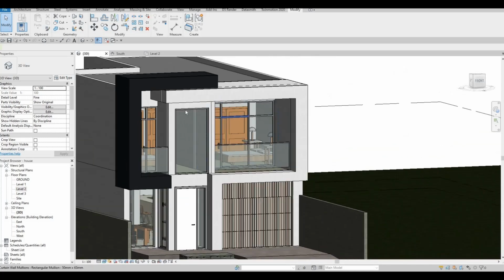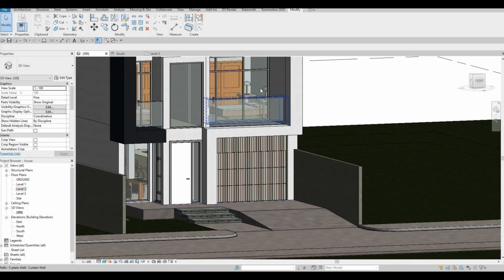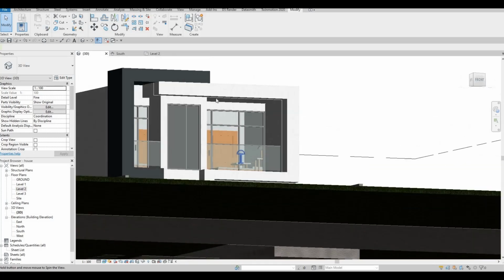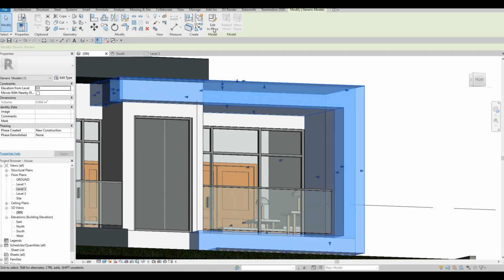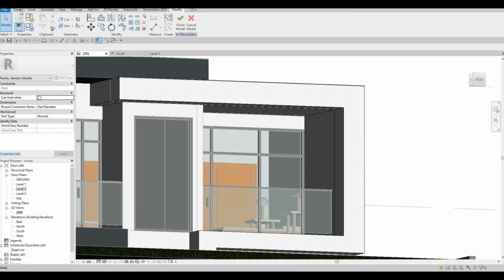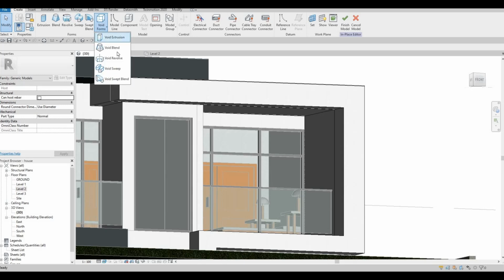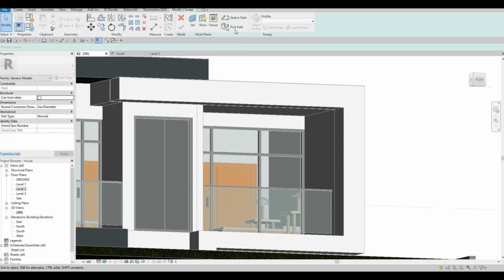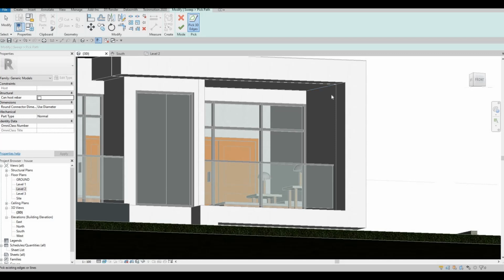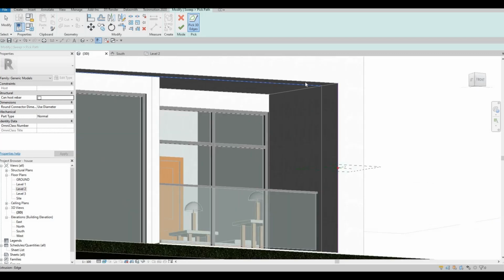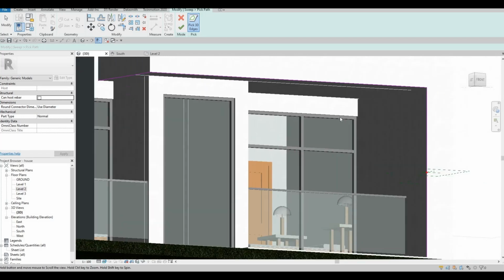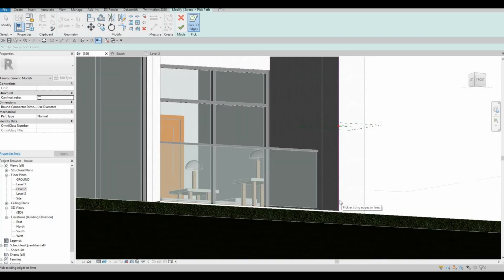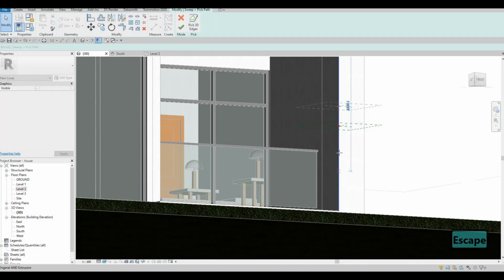And then what we can do is create something similar like this in here at the top here. So let's select this one, edit in place. We could void sweep, pick path, and we're going to select this path right here, something like that. In terms on here, we could just move it until this part right here.